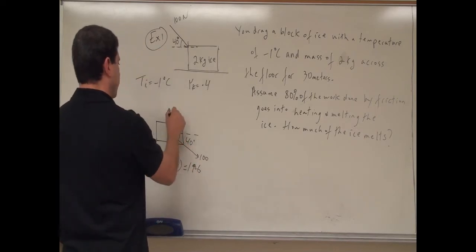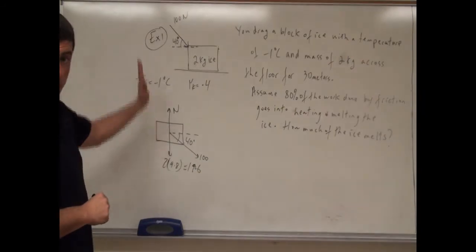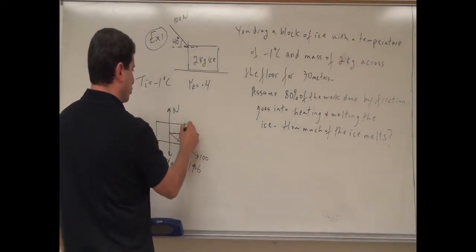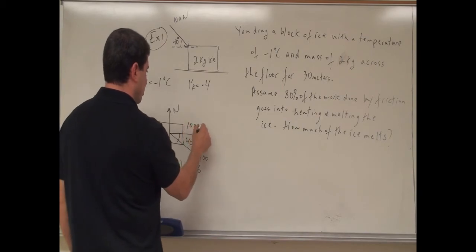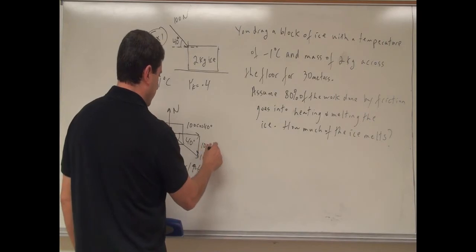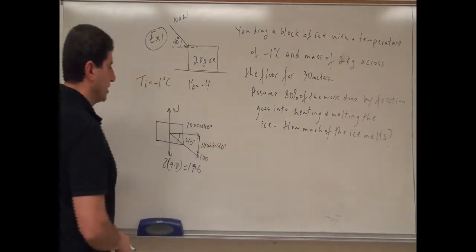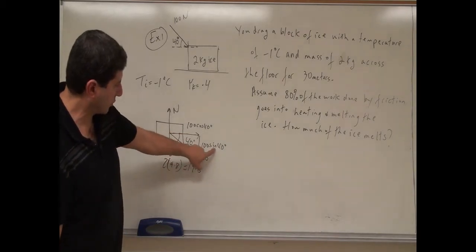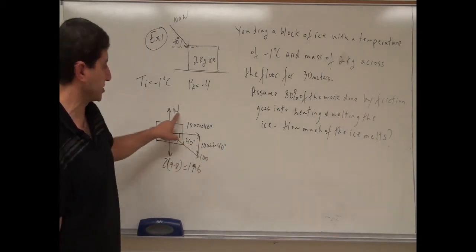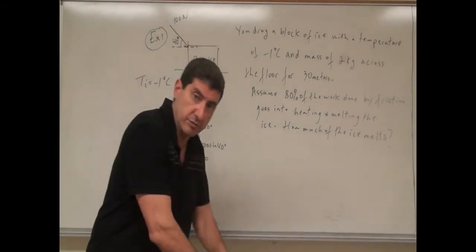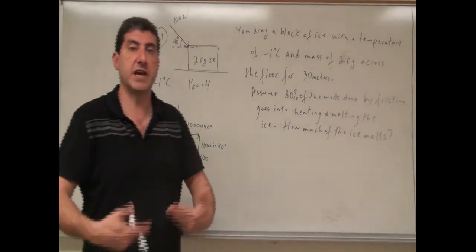Then we've got the normal force of the ground supporting the block. So we can break your force into a horizontal component, 100 cosine of 40, and the downward component, 100 sine of 40. So then what's going to happen? The downward component of your force, the 100 sine of 40, is going to cause the normal force on the block to go up. Because you're pushing down on the block, it's going to make the block feel heavier.